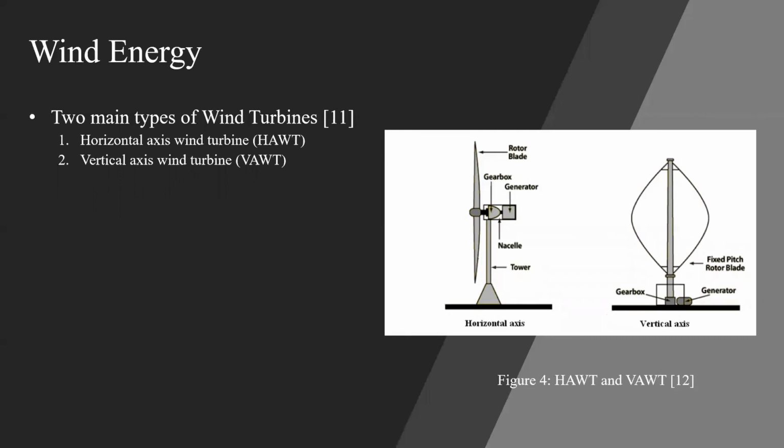components. The vertical axis turbine is built a lot closer to the ground, which means the maintenance is a lot easier to perform. And it can also perform really well in high winds. These turbines are normally found on high mountains or cliffs where the wind speeds can be dangerous. However, they aren't as efficient as the horizontal axis ones, as the wind speeds aren't as high closer to the ground.